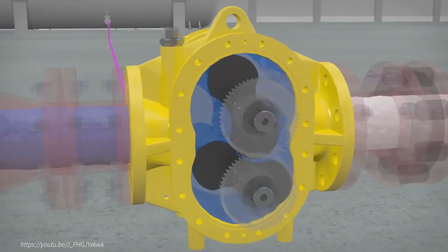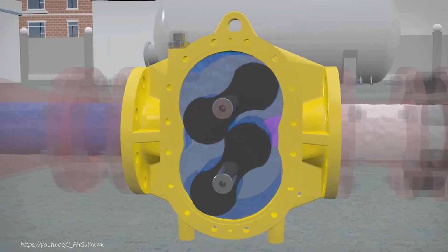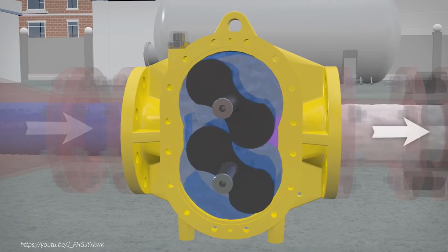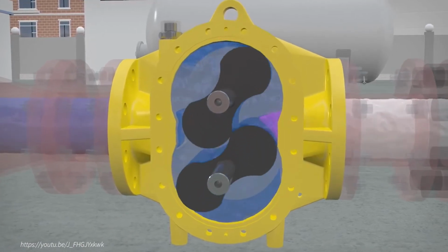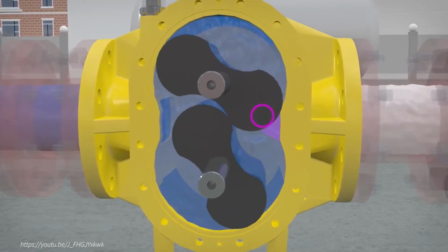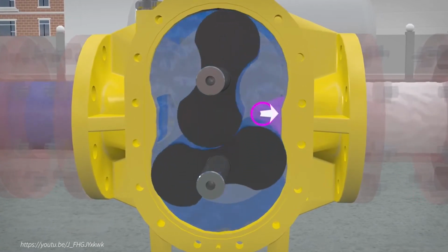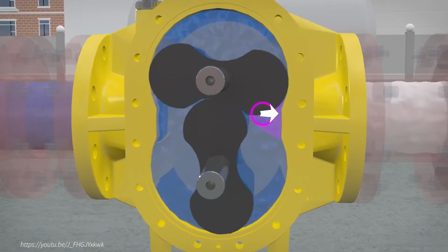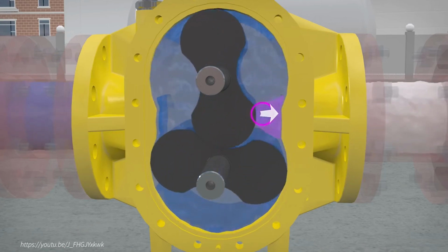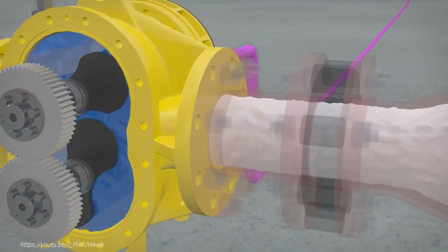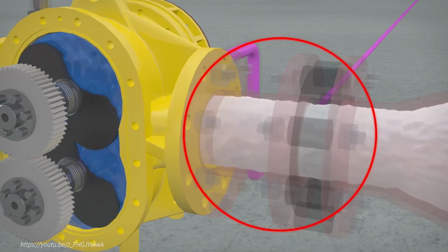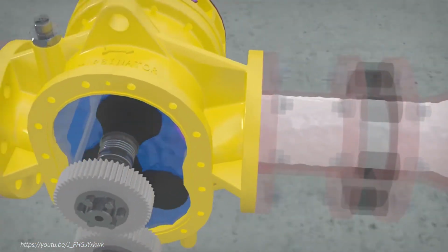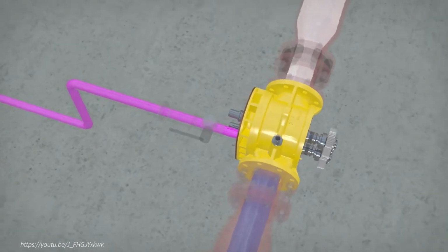Each full revolution of the water pump moves a fixed volume of water from the inlet to the outlet. At the same time, because the foam pump is on the same shafts, it sucks foam at a related fixed volume and pushes that through a port in the body into the water stream at the outlet side. This results in a 100% accurate mix of foam solution, regardless of any outside influence. In other words, the Turbinator is a positive displacement device.